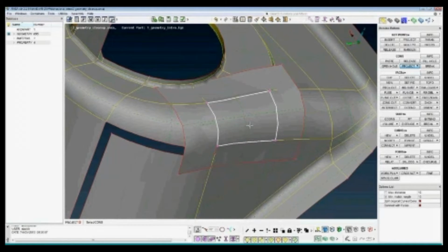I middle click to confirm to proceed in the function. If I selected the wrong cones, you can always deselect with right mouse button. So deselect with right mouse. Okay. Middle click. And so now say select face. And this is the face that will project the lines on. I select the face, middle click to confirm.